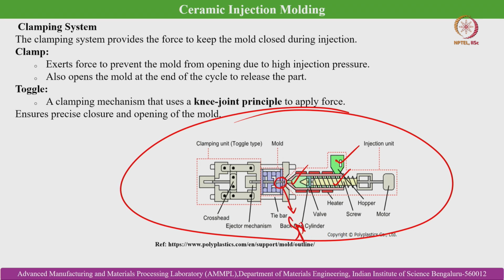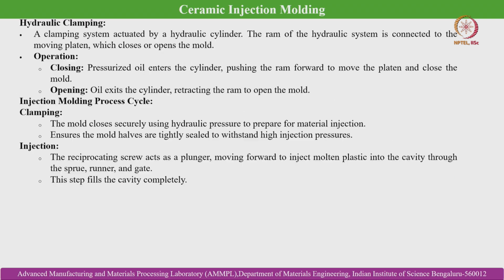It takes the melt from the nozzle, and it has to be ensured that none of the melt gets leaked, and that is why the sprue inlet diameter is kept slightly bigger than the nozzle exit diameter, and then this is the mold cavity, that is, this is the mold. So, this is the clamping unit which keeps the mold in a locked condition during filling of the mold by the injection of the polymer or the polymer metal or polymer ceramic mixture.